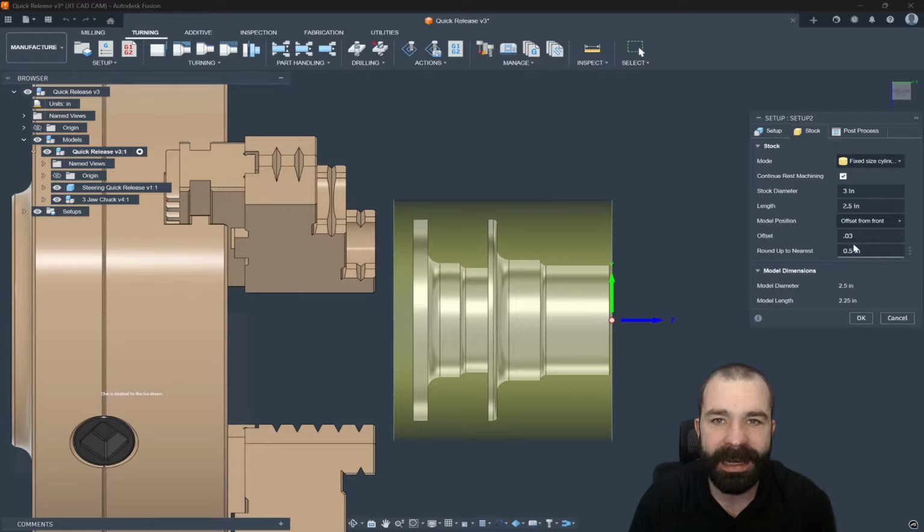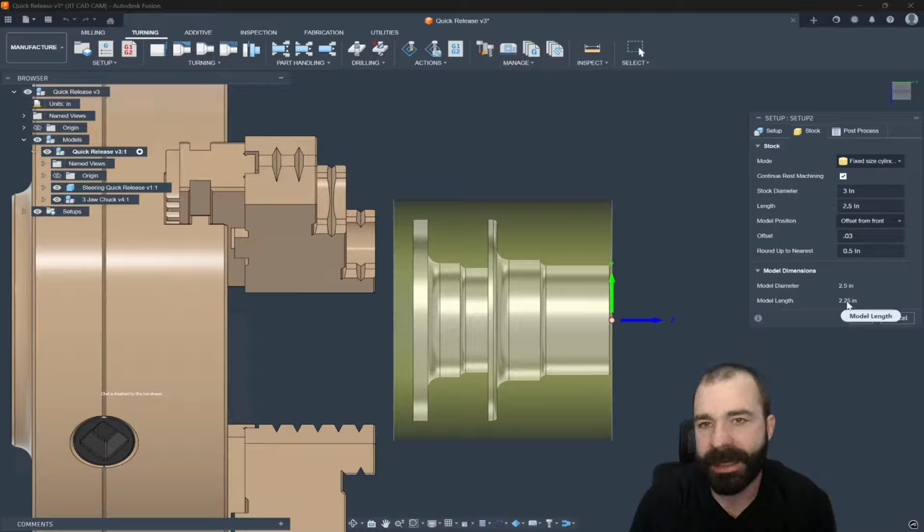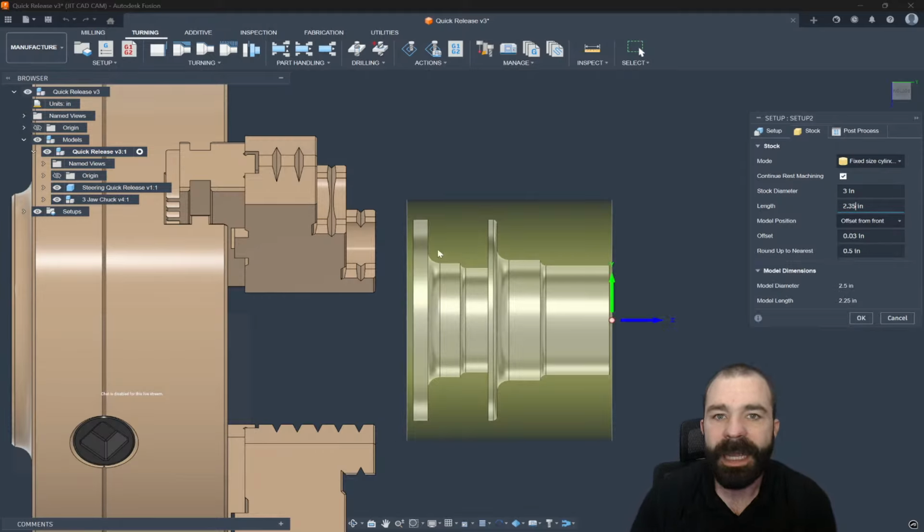Well, I can add in 30 there. That's 28. And then if I'm going to use something like a 100 or 120 thou part off tool, I'll throw that into my numbers as well. So I could actually get away with here, maybe taking this all the way out to 2.35, for example. And as you can see, that gap in the back is much smaller.